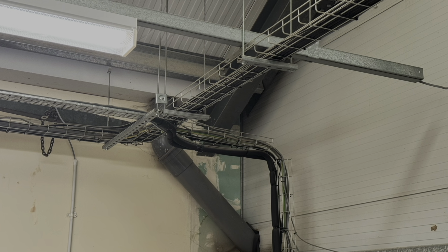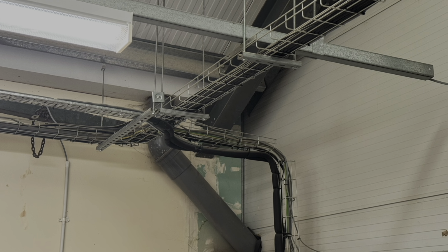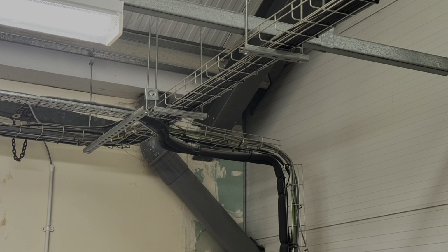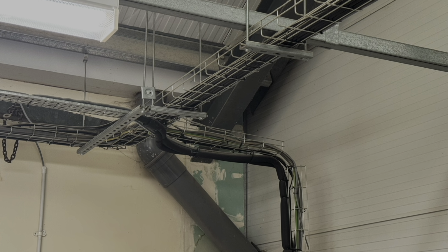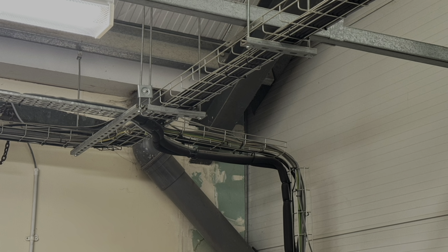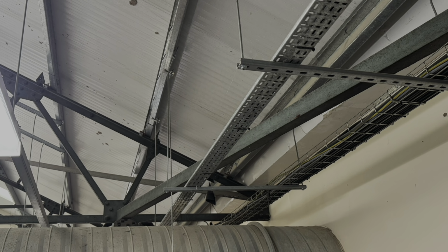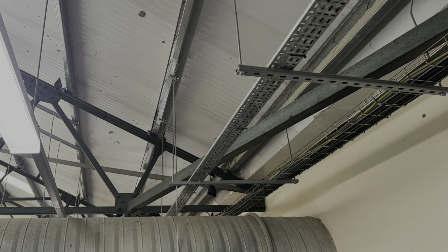But if you ran baskets side by side with 50 mm between the cables, this would not be sufficient, as basket is not a suitable barrier for the higher voltages present. So it will not give separation. This means you would need to either use a suitable barrier or keep a distance of 150 mm between the basket. Let's have another look at our drawing from earlier.